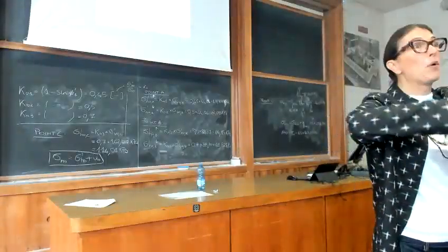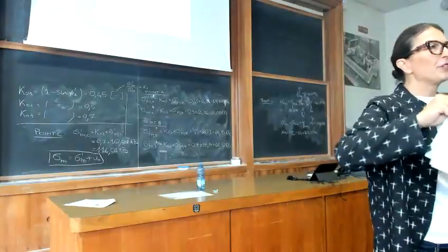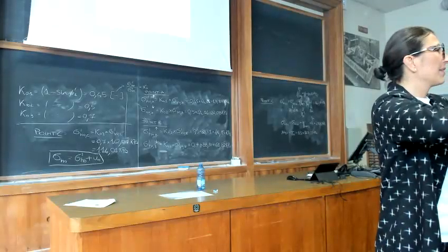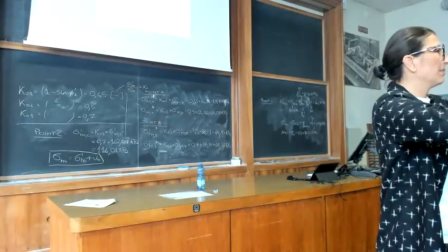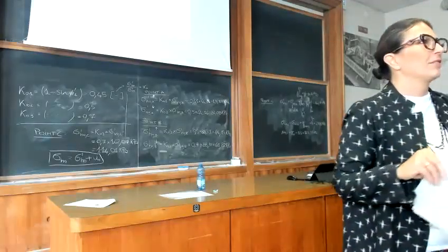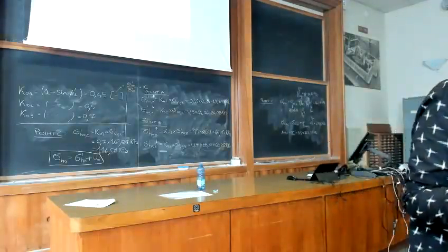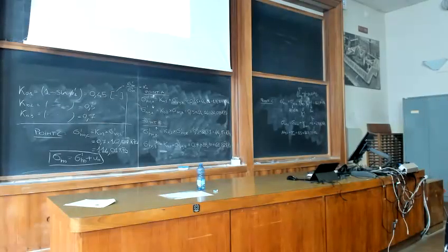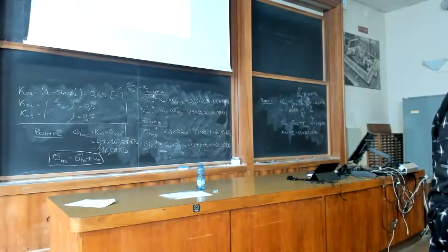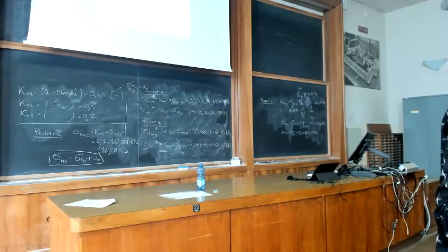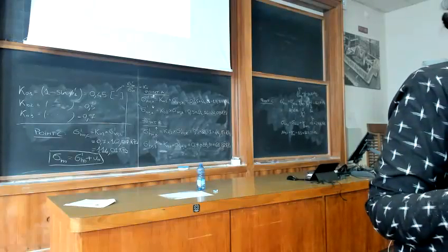We superimpose from a theoretical point of view these two continuum materials, it is a superimposition, but the mechanics is different. In particular, water pressure is isotropic. So pore water pressure has the same intensity in all different directions.